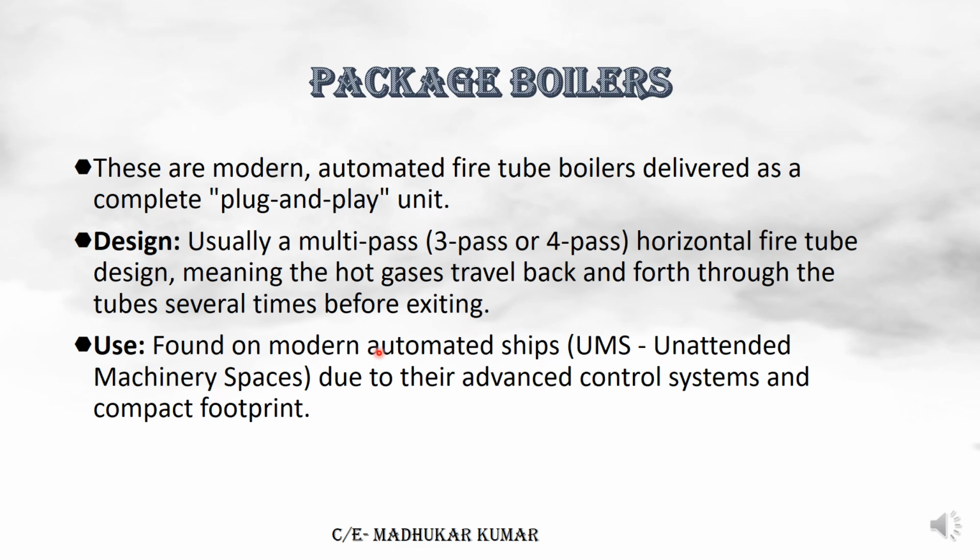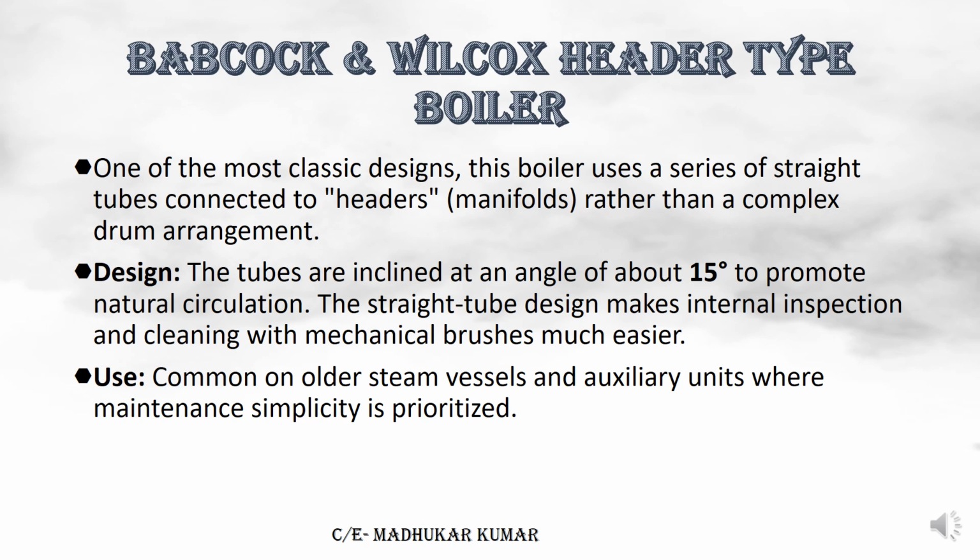Found on modern automated ships, UMS ships, and these have an advanced control system and compact footprint. So this is something which is very much utilized for the packaged boiler. So these are basically your fire tube boilers. Now we will go for water tube boilers.